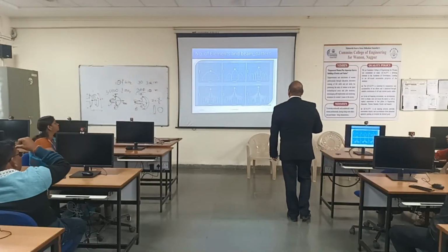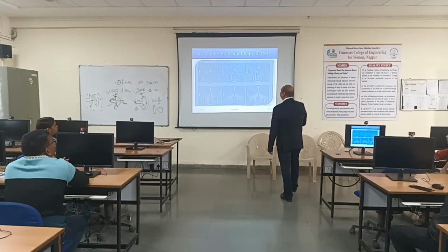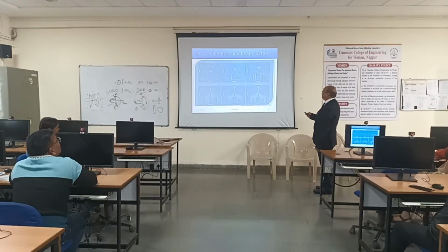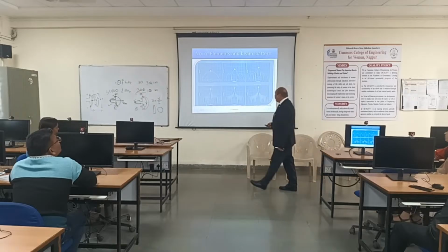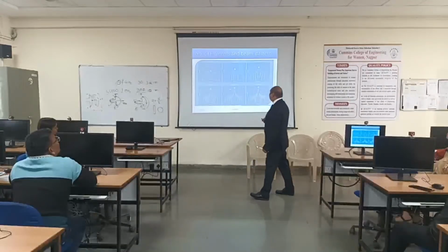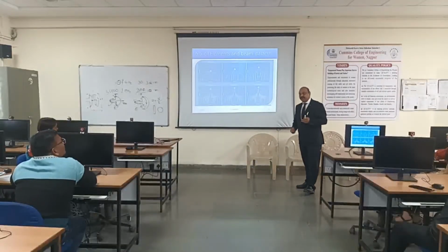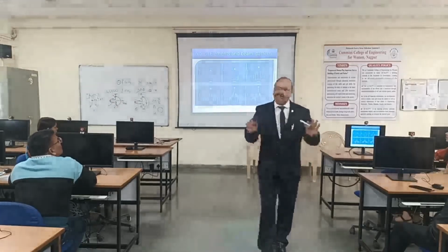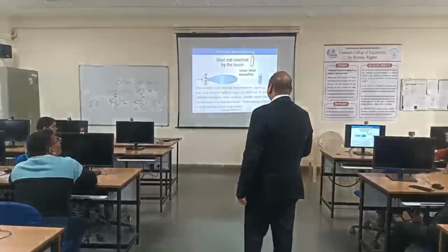So the number of elements and the beam forming. Let us say here is the 2 element. You are getting this maximum at 0. Then if we take 4 elements, what will happen? Gain will be increased. So gain will be up to here. The gain has been increased. Why? Because the number of elements increased. If it is an 8 element, then gain will further increase. Now if you go on increasing the number of elements to 16, 24, 32, gain will go further and further. The more antennas you use, the more gain will increase. Simple logic. Next.